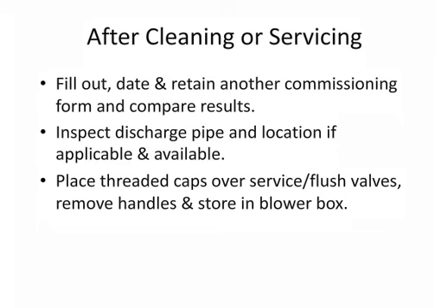Always walk around and inspect the discharge pipe and that termination location if you can, because I've seen a couple of instances where, golly, things have grown over, or the beavers have come up and built it into their den and you can't get to it. So if you have that ability, always take a look at the discharge piping, make sure everything's in good shape.